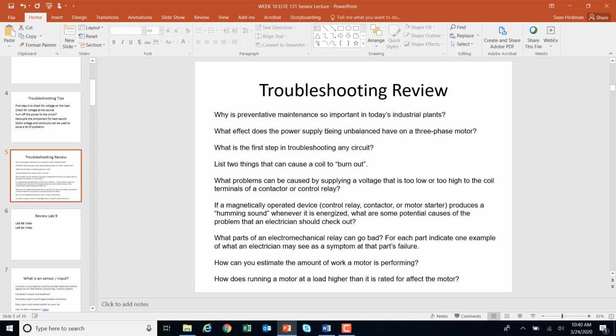That motor's not going to run very well, though, because it's supposed to have 3 phases. So you're supposed to have voltage between L1-L2, L1-L3, and L2-L3. But it's only got voltage between L2 and L3. So what's going to happen? Well, it's going to run hot, and it's not going to run very well, and you could damage that motor. But that's what single phasing is.